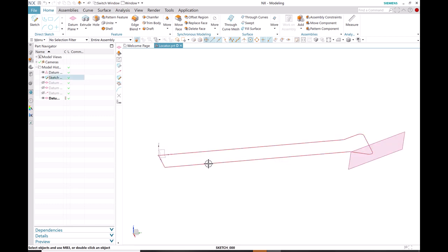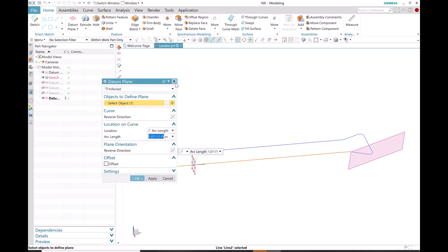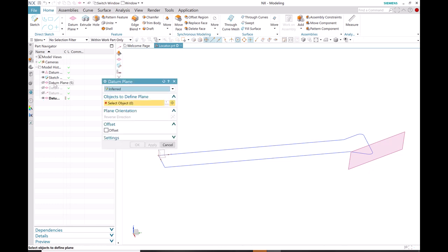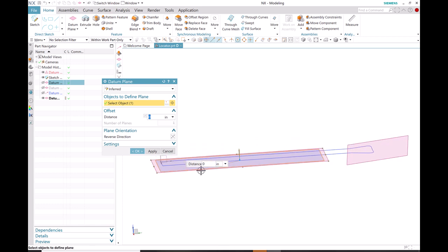I need another sketch down where the extrude would otherwise end. So I'm gonna, sorry, I'll mark a datum plane. So I know I hid this plane, but I should still be able to select it. So I'm gonna mark another datum plane that's 0.748, and in the other direction, so there.